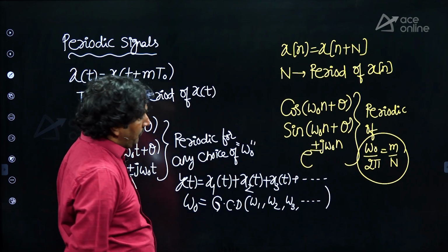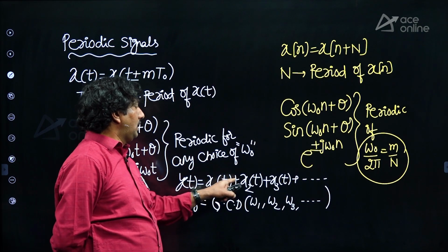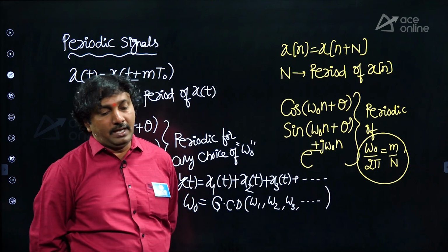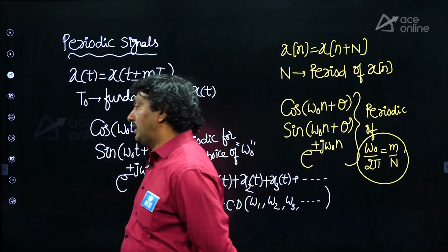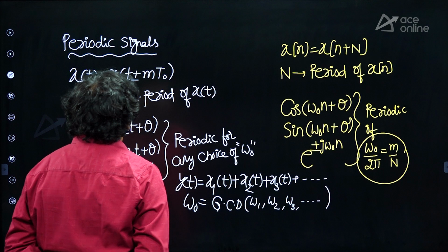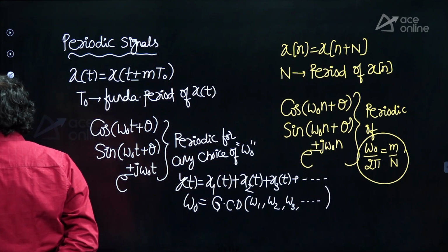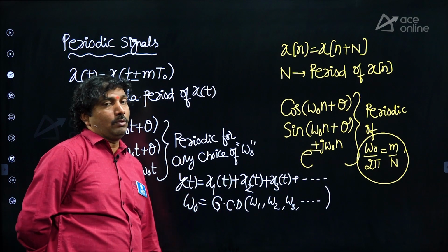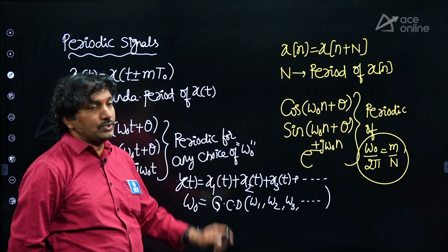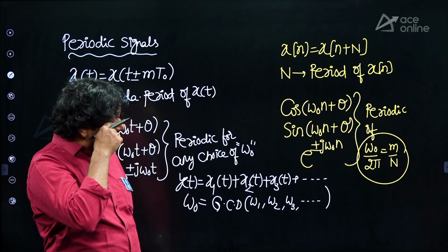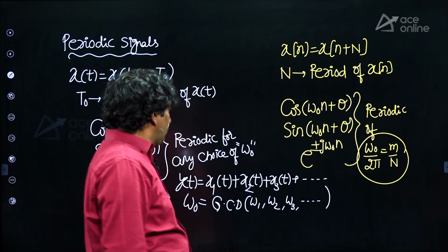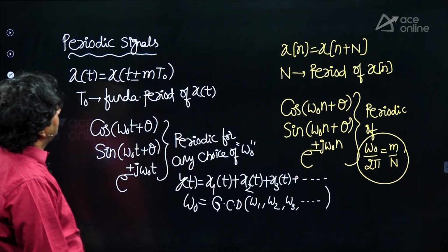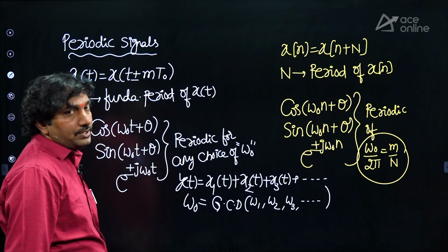If we are assuming the first signal is periodic with time period t1, then t2, t3, you are aware omega naught is 2 pi by capital T, the fundamental frequency is 2 pi by capital T. So it may be continuous or it may be discrete. To decide whether the overall signal is periodic or not, use that logic: GCD of individual frequencies. So this is also one regular question you can expect in the exam. A compulsory question will be there on periodicity, compulsory model.